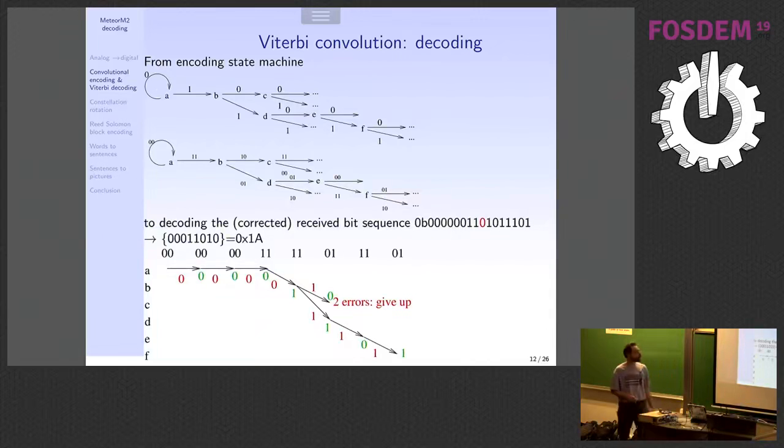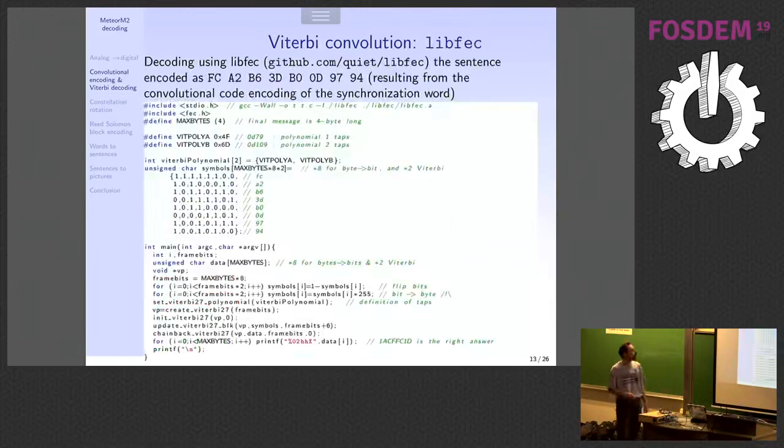So OK, we've understood Viterbi decoding. So now, well, we can go for it. So yeah, sorry. If you don't want to go into all the math by yourself, you have libfec with you, and by K9Q, and libfec will do the job for you. Here I put for you a very simplified chart of running libfec for Viterbi decoding. Just don't make the same mistake as I did. libfec will not take as input 0 or 1. You need to feed it 0 or 255. It's working on a byte.